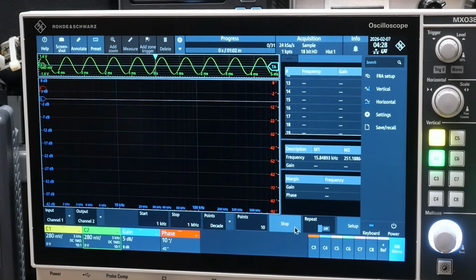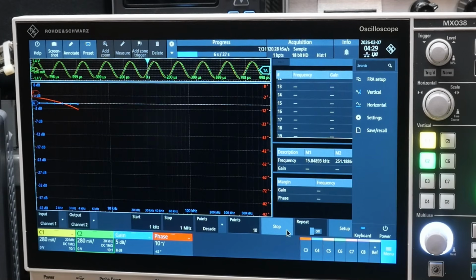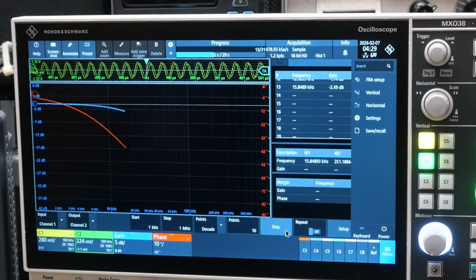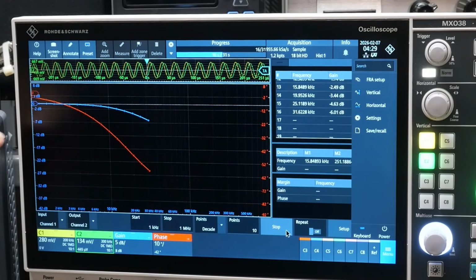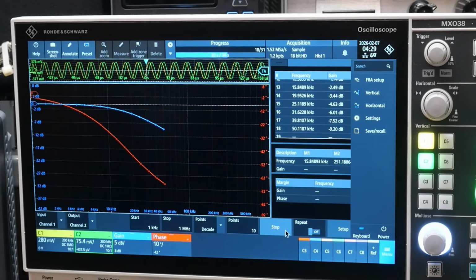That's a previous measurement. So up here, we can kind of watch what's going on. You start out with the input and the output both identical, a gain of 1. And then as you start getting a resistive division, you'll start losing dBs. So we're down now minus 7 dB here. And we'll continue to lose gain because we will be killing high frequencies. Remember, this is a low pass filter or a high cut filter.